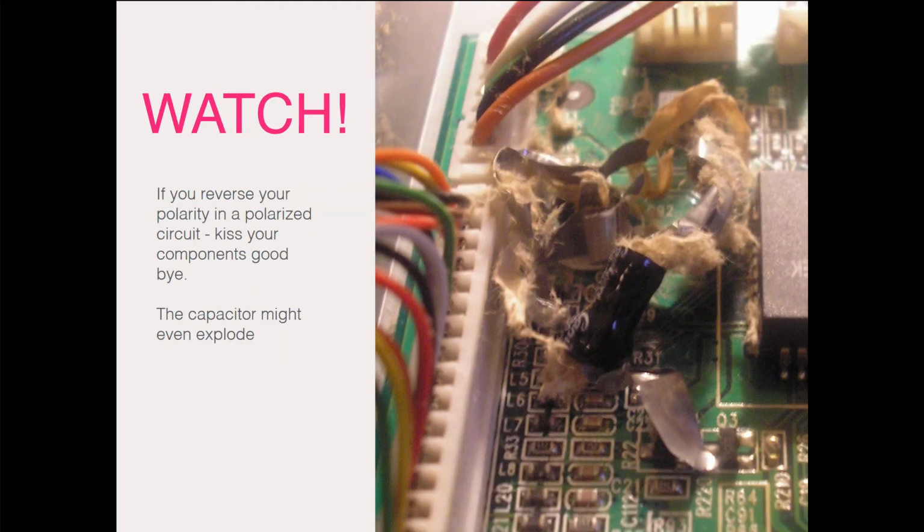If you put too much voltage through a capacitor, you can blow it up. And if this happens, you can kiss some of your components goodbye, because you just ran power in the wrong direction all over your circuit, and the capacitor might even explode. No fire will happen, generally, but there will be a nice loud pop, and your capacitor will spit its dielectric material all over your board.